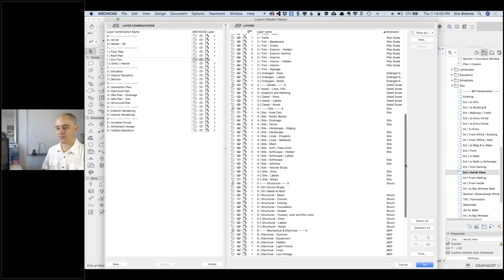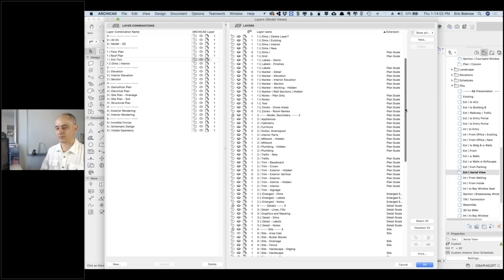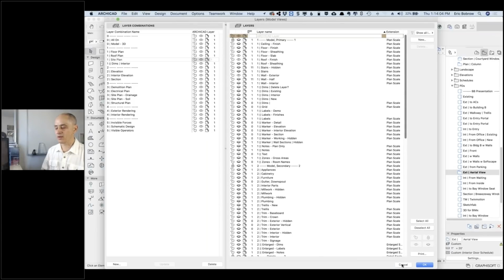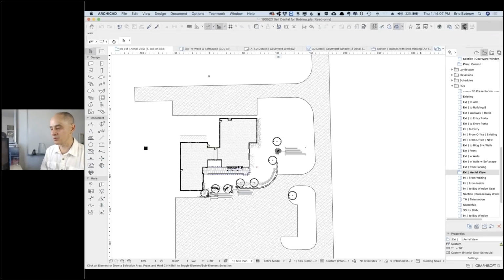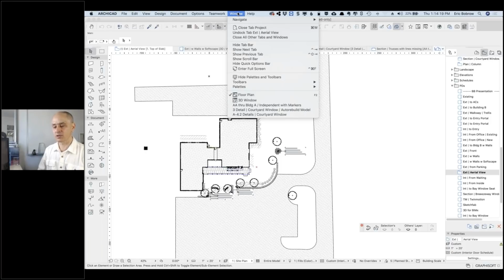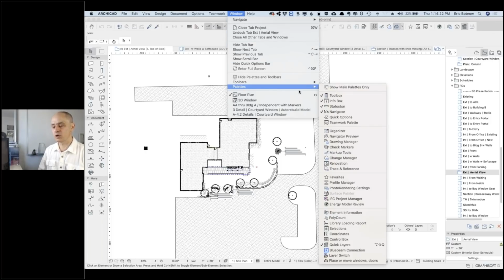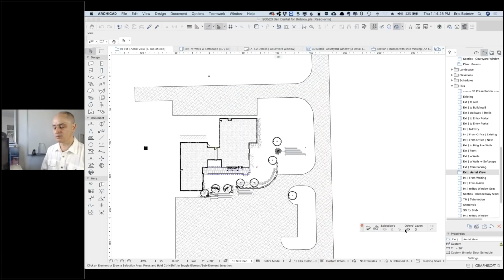That's why, if you could select something and then toggle other layers. Oh, okay, that's what you meant by toggle. Okay, so we go to our quick layers here. This is excellent. Since I am always training whenever people are watching, it's available from the button in the standard toolbar in the US. It's not in the standard toolbar in the international version as far as I know, but you can always go to Window, Palettes, Quick Layers. It'll open up this layer palette. And then one of the things you can do is toggle what's visible and what's not.